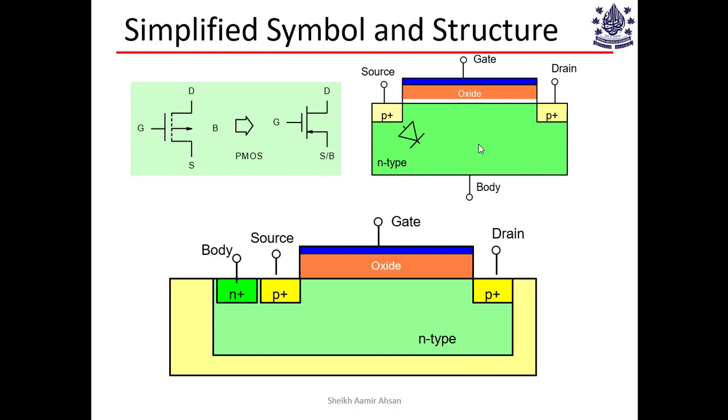That's totally opposite to what you need for an NMOS. Now, how do you create this n-type body in the case of a wafer? Notice that whenever we start with fabrication, these MOSFETs are generally made on some substrate. So this here is a substrate. This is your typical p-type substrate that you'll often see available in the market. The substrates are typically p-type.